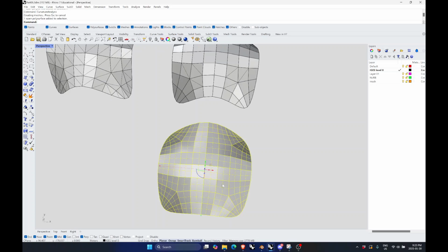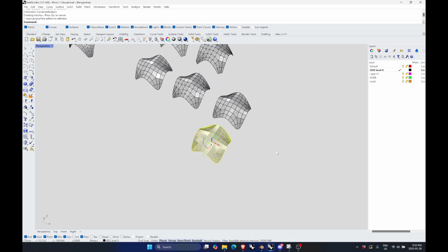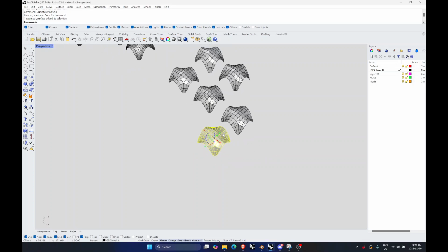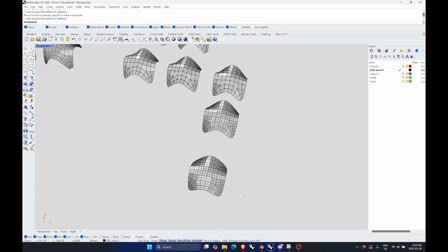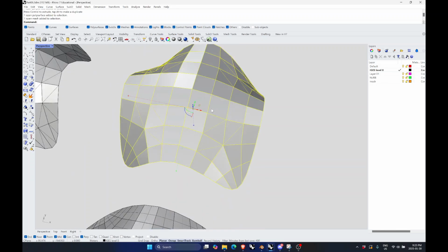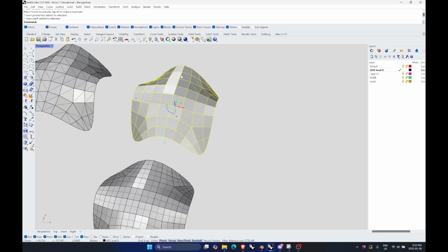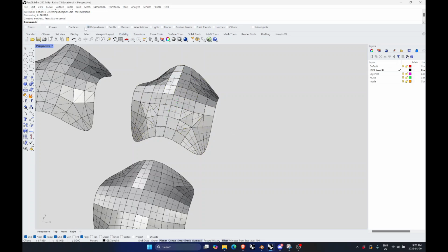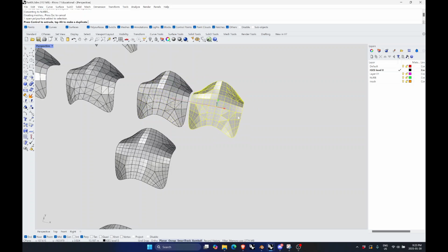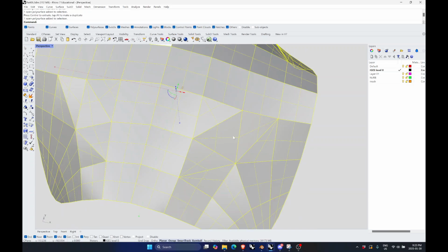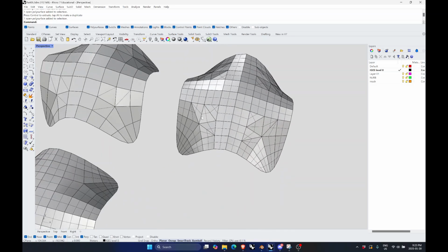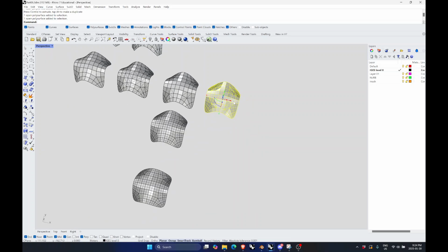So let's go back, and we've got this open poly surface. Now let's say I want to fabricate this. Let's just make a copy. Always keep your original geometries. In fact, let's try to convert this to NURBS, the one that we triangulated a bit, not completely triangulated. Let's see what it gives us. Yeah, so you can see how it's developing triangulated surfaces. So it's a poly surface.